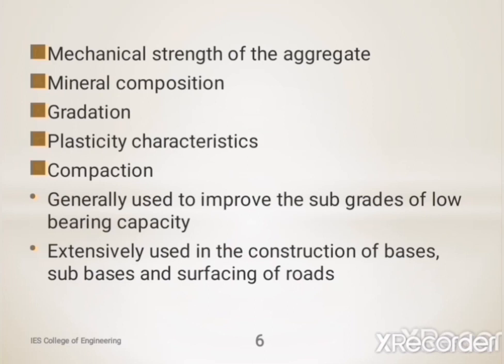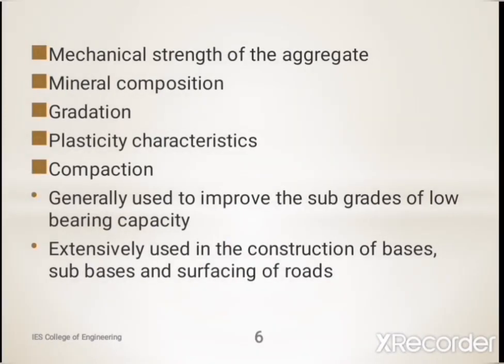Then in the case of base courses, plasticity characteristics are different from the surface soil. Soil in base courses should have low plasticity, to avoid excessive accumulation of water and the resulting loss of strength.